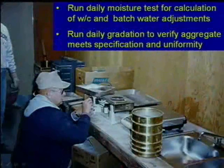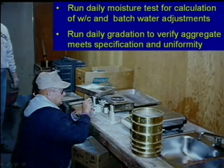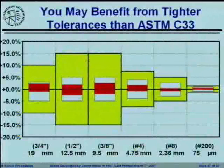Right? As we mentioned before, daily moisture tests are going to help you in controlling the water to cement ratio and batch to batch water adjustments. Daily gradations are going to help you to meet specifications in terms of aggregate gradations, in uniformity, making sure the concrete is going through quickly.